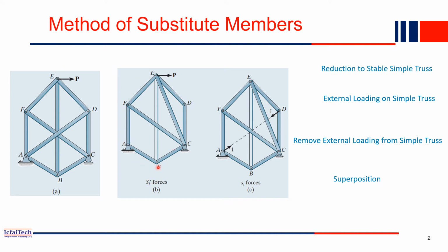We can solve this truss using the method of joints. Starting with joint A, there are two unknowns, so we can solve it. Similarly, coming here also two unknowns will be there, we can solve that. Here also two unknowns are there, we can calculate both. Then if any zero force member is there, that will be separated out anyway. So by just making a simple truss, we can determine all the values here.